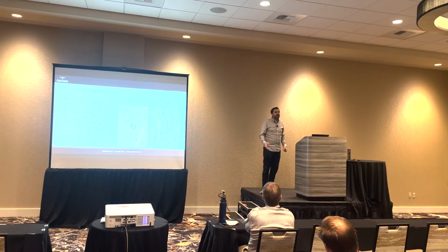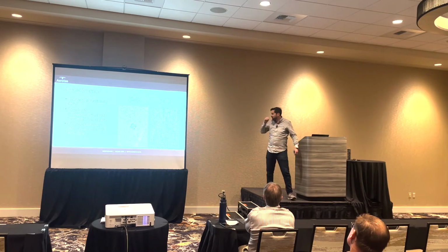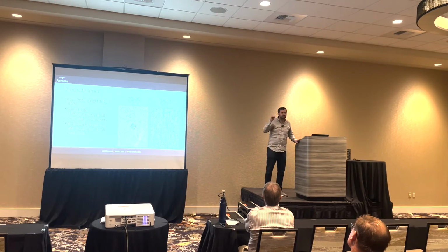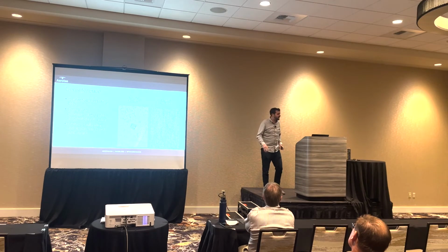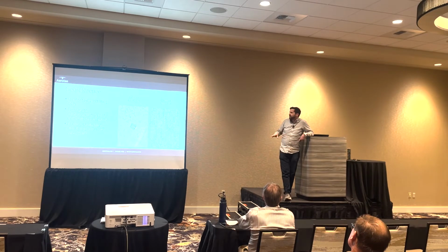Likewise, you often have to localize to a project. I'm from California, where things move by a tenth of a foot every year. And so most projects are going to be localized to some known point to make sure that all the prior data matches up with all the current data. So one of the simplest, cheapest, easiest, and most reliable ways is to use ground control points. And that means your ground control points to actually make sure that everything else aligns.